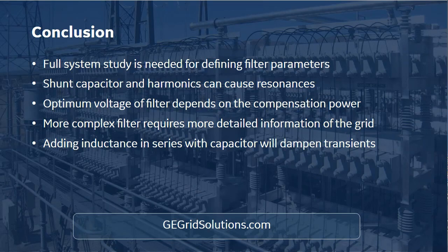If we have a parallel resonance, it means that the harmonics are coming from somewhere that is in parallel with the capacitor bank. And if it's series, then you have the series connection between, so you have transformers and upper voltage level and again transformer and so on. It's just the name of the resonance, called series and parallel.